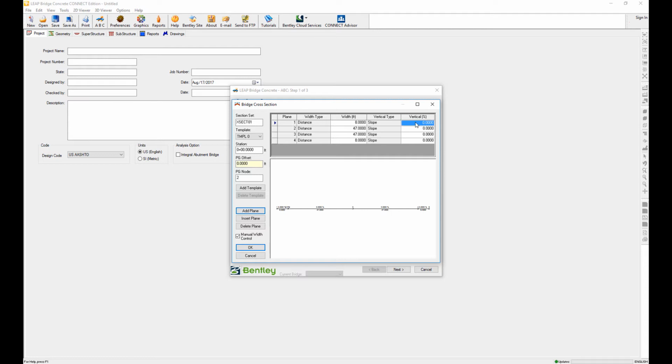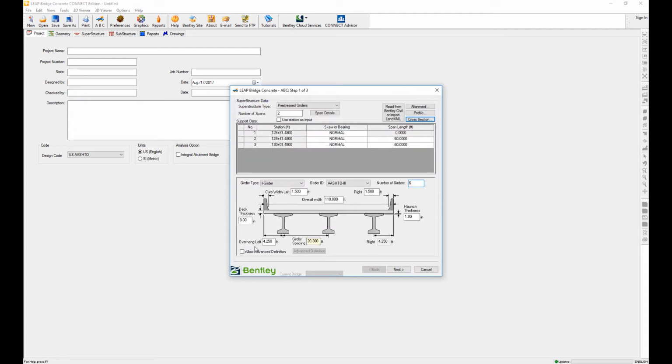Now pay attention to the slopes. The first slope is going up from this point to this point, then still going up in normal crown, but then also from here to this point is going down, and also is going down. Okay, so be careful with that level symbology. And then the profile grade line that was running on point 2 actually now is running at the center of the bridge, so this will be on point 3. So saying that, I have defined the full horizontal and vertical geometry of the bridge plus the cross sections, and